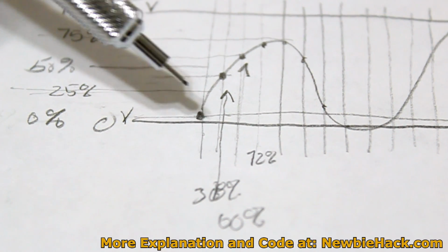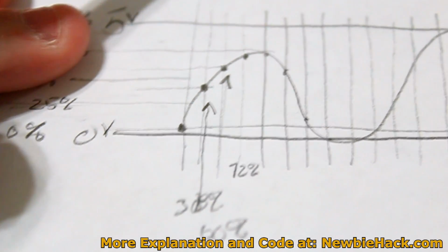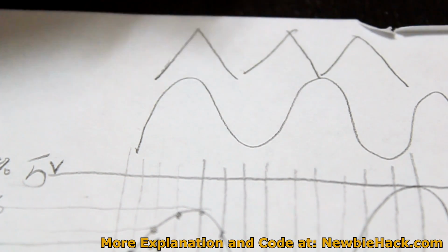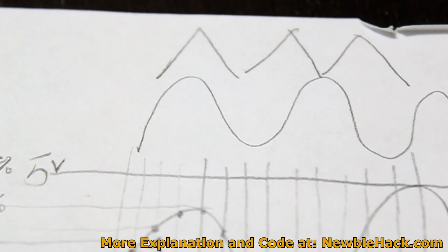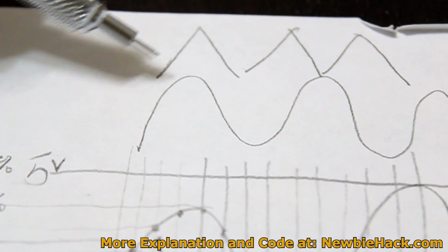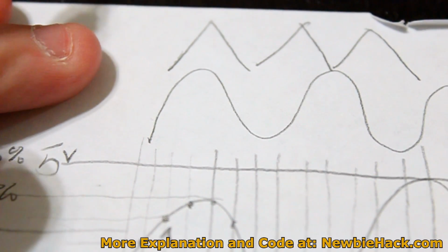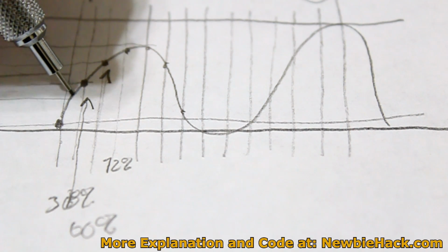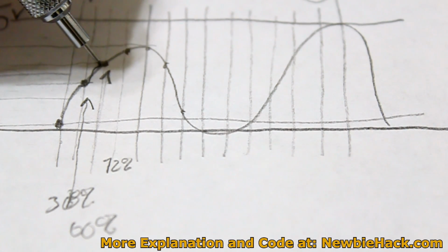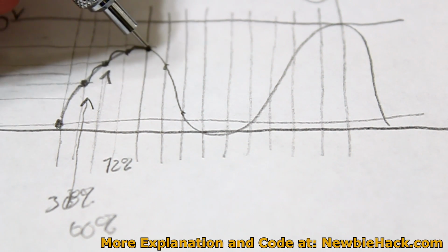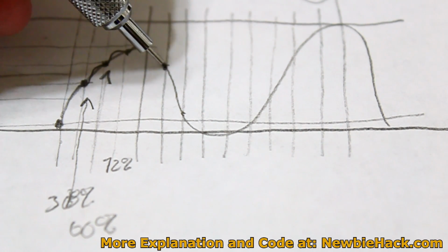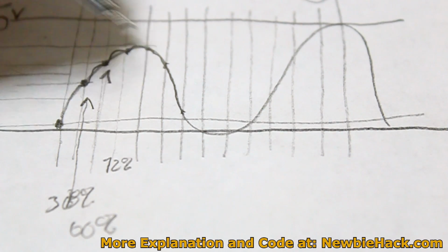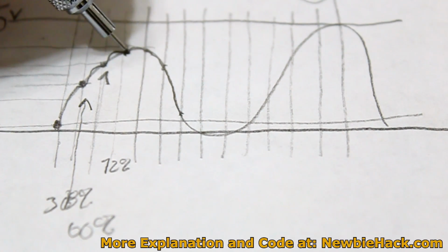But it could be a waveform that is constant. Maybe it's a sine wave, maybe it's a triangular wave, and you can create any kind of waveform with a microcontroller, and it would be an approximated analog. And when I say approximated, you can imagine that the capacitor is going to charge up, and then level out and then charge up again. So it's going to be a bumpy waveform, and depending on if it's rising or falling, you'd have some bumps in here.